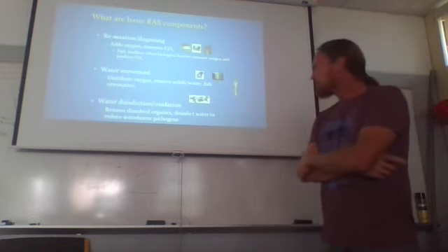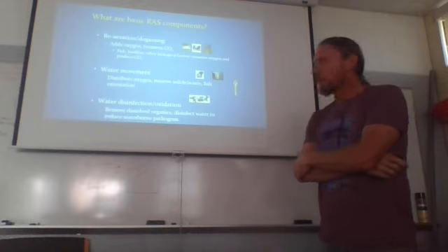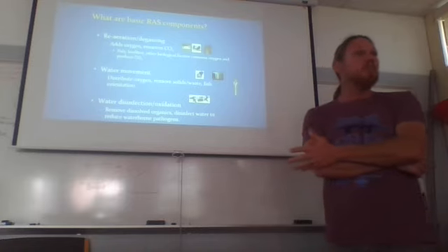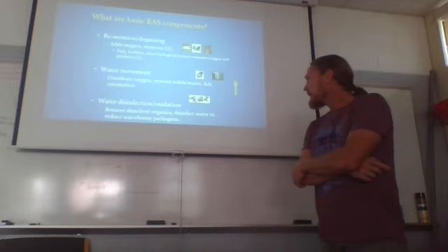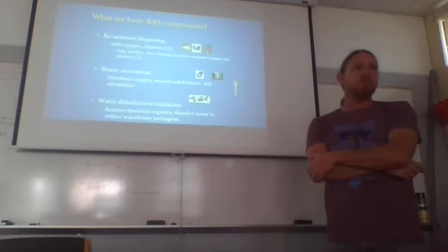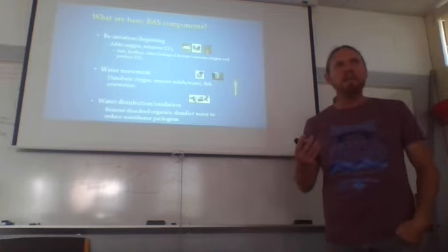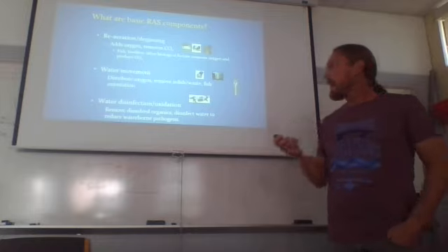So one common technique is an ultraviolet sterilizer. There's a trade-off with it. It uses some power. They're pretty expensive. The flow can't be too high through them. If I see an ultraviolet sterilizer that says it can take a lot of water flow through it, I'm skeptical as to how well it's going to work.